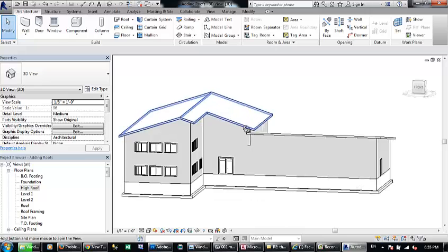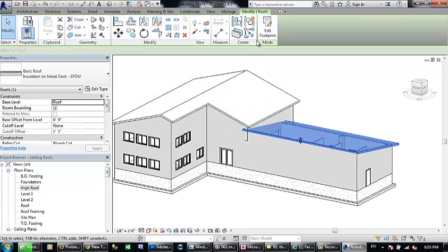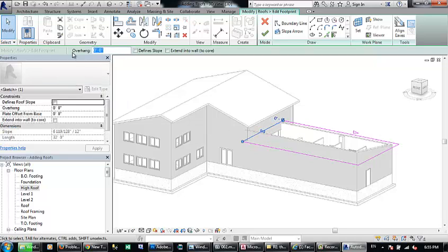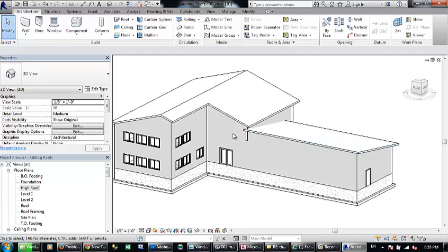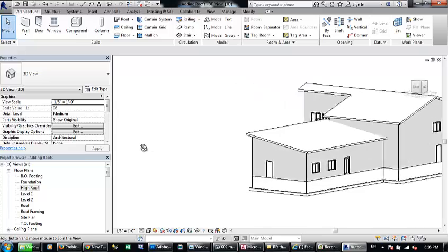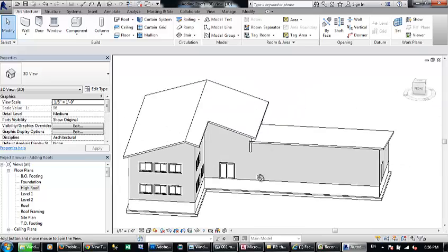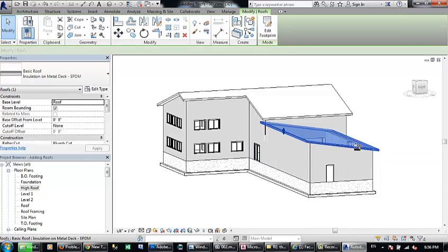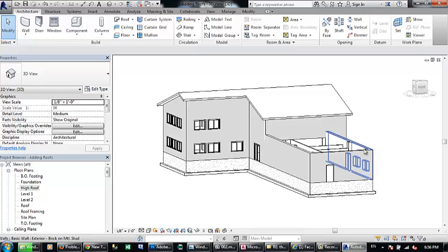You can also set it with negative values. I haven't tried this before, but let's try to set it as a negative value, -0.5 feet. Then click finish. It's okay. So now it's not extending too much to the inside, and it's looking properly. And now if you return back to the roof and you delete it, the walls will come to their original state.